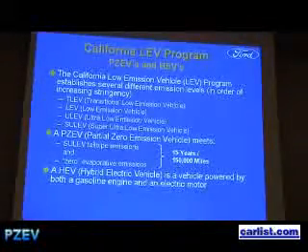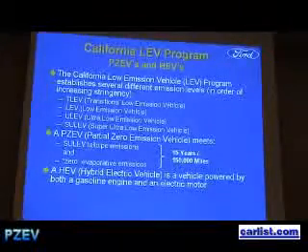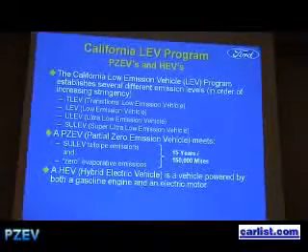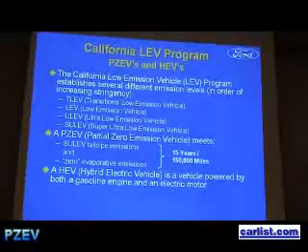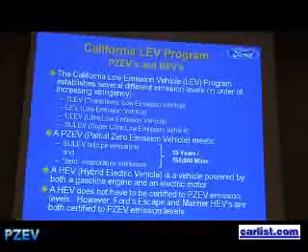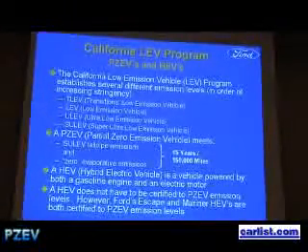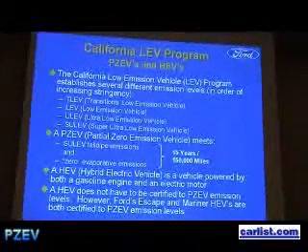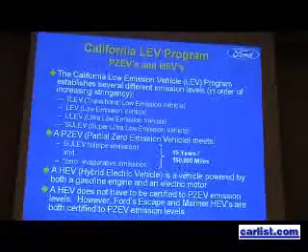A hybrid electric vehicle is a vehicle that's powered by a gasoline engine, but also has an electric motor in it. It typically has regenerative braking, so when you step on the brakes, that energy is absorbed back into the electric motor and recharges the battery, and that's why you get the fuel economy benefit. A hybrid doesn't have to be certified to PZEV emission levels. So just because it's a hybrid, it may or may not be a PZEV. Fortunately, our current hybrid products, which are the Mariner and the Escape, are both certified to the California PZEV standard.